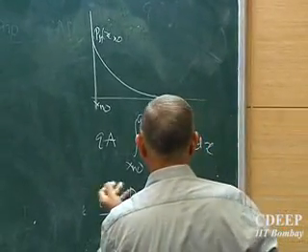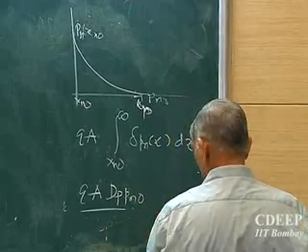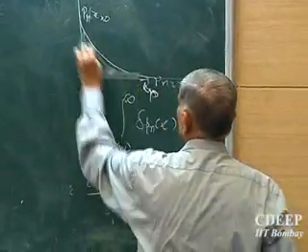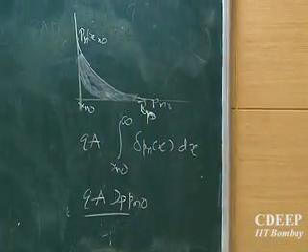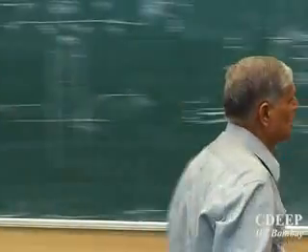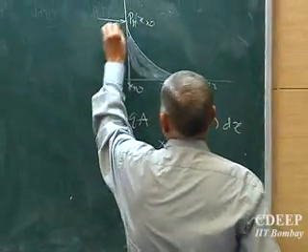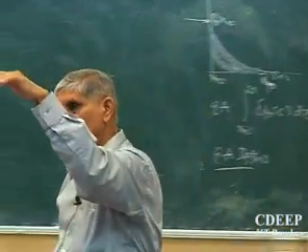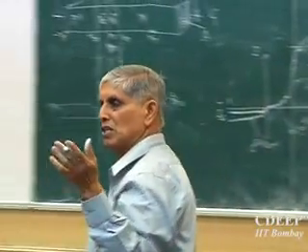Sorry, how much it will be? No, integrate the charge in this. Net carrier concentration multiplied and integrated over that region is the charge now injected into the N region from the P side. Total charge injected. Please remember what he is saying. I think I did not make it clear. I have injected holes from the P side into the N side. They are decaying because of recombination and diffusion terms. But in steady state, the profile remains constant. So how much is the injected charge? Area under the curve. So integrate it out.